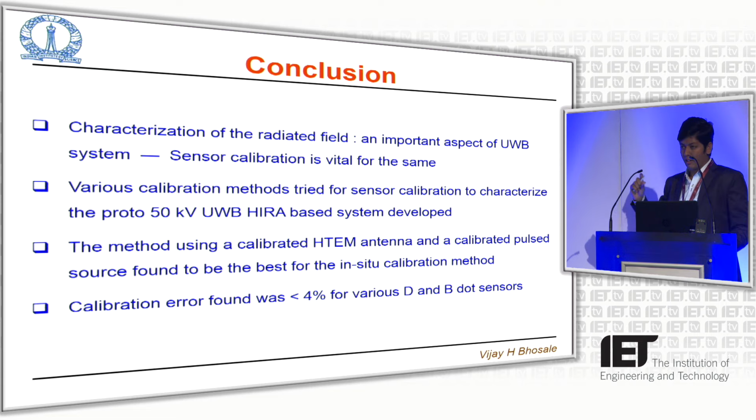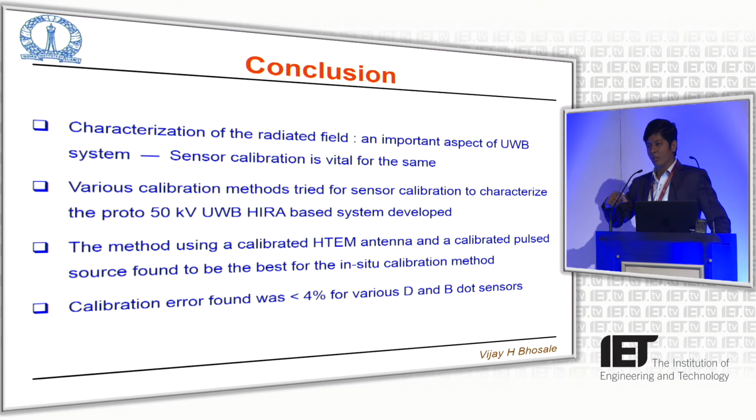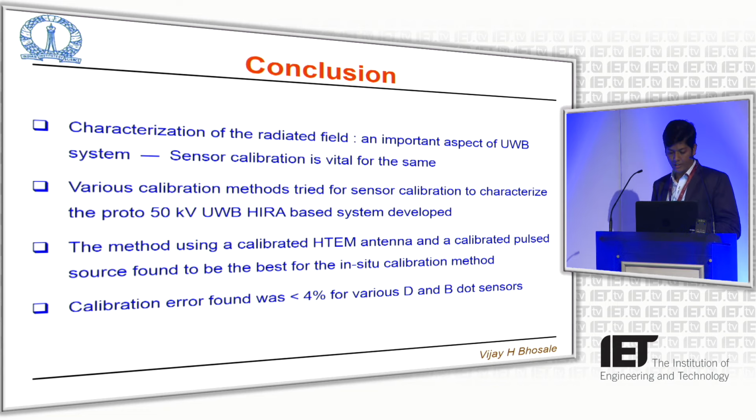Calibration is everything, because doing experiments at picosecond rise time is extremely challenging. And if the environment is not anechoic, for example free space or somewhere else, sometimes bouncing pulses will come, and they will be picked up by the sensor. So calibration is an important part. That's why the sensor needs to be designed properly.